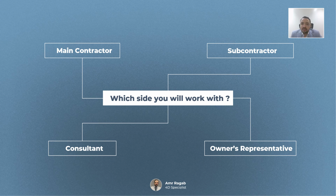So for example, if a structure is scheduled to be cast before the foundation is ready, the 4D video will highlight this point and you can review it. Then you go back to the planning team and edit this point. So it's a quality and constructability check tool for them. Consultants don't build, but they make sure what is built makes sense. 4D gives them that power.